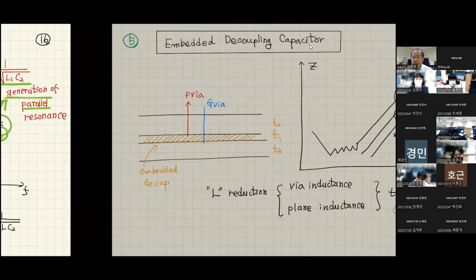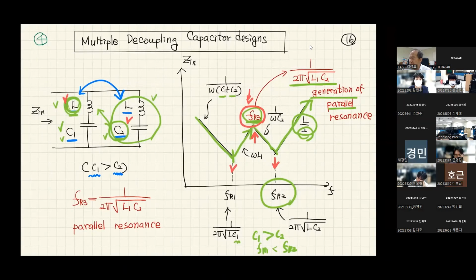But still, I want to emphasize that at higher frequencies, inductance is continuously increasing and impedance is increasing. This is the gigahertz range. That is where we want to send very high frequency data, especially between GPU and memory or between GPU and CPU. So we have to fight against this inductance.